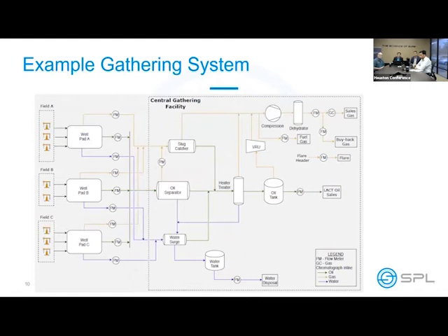All right. Going to take us through our gathering system there, Bill? So what's pictured here is just a typical gathering system that we may see for allocation. We start on the left-hand side. We'll see at the field level, this could be wells, it could be fields, it could be different injection points into the actual system. What we have here is reflected in a multi-tiered system where we would have the well pads that are next in the diagram, and we would allocate those flow meters. That's what FM is going to stand for here. We would allocate those flow meters back to the well level or the field level, A, B, and C. And then ultimately, at each one of those flow meters, we'll have a volume and specifically probably an analysis also.